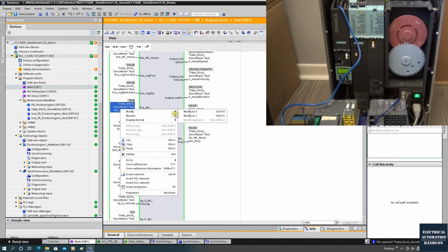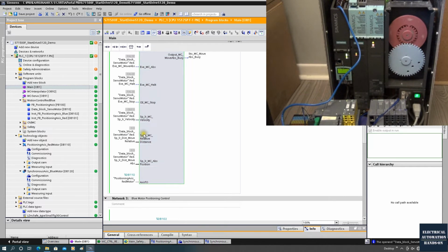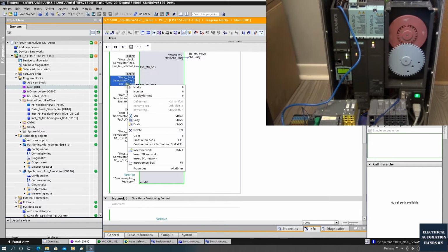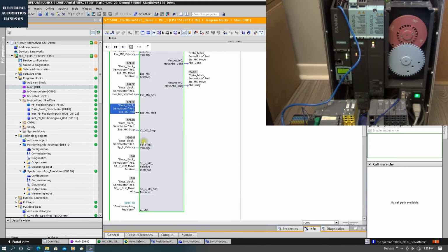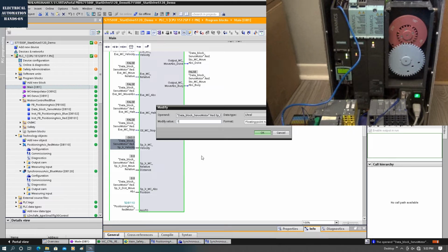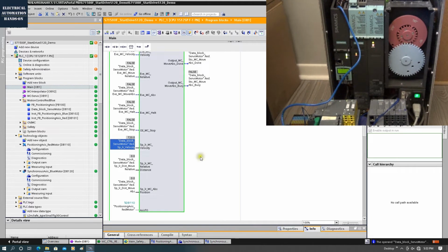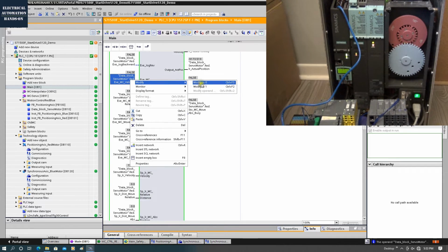Okay, if I'm going to stop this axis, I have to use the MC halt or MC stop. Okay, halt is a gentle stop. I trigger, we'll see the motor gently stop. And now if I change this target to a higher speed, for example 720 positive value, and once we trigger, the motor will run in the forward direction 2 revolutions per second.